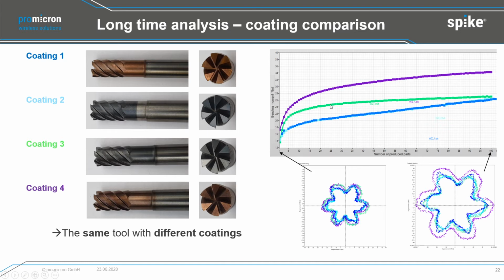There might be a discussion between experts, why some say the green is the best, but some say the blue ones are the best, since the slope for the green one is definitely the best. Do you remember the picture of the green one before? There we already had a scrape in the helix, in the cutting edge, and this was causing the higher force straight from the beginning. So here the customer already had a very easy feedback by having the picture and the force value that the blue ones had the best performance.